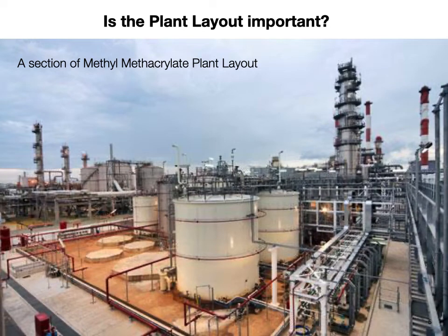Alright, so is the plant layout important? The answer is of course yes, because it has a direct relationship with efficiency of operations and cost of production. A poorly designed layout will result in inefficiency and losses, which we don't want. It is important also to design the layout in such a way that it is flexible to changes, because you don't know what's in the future, but the plant layout will stay within 20 to 40 years of building.